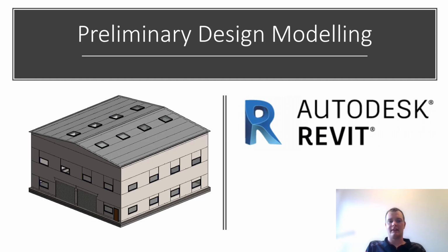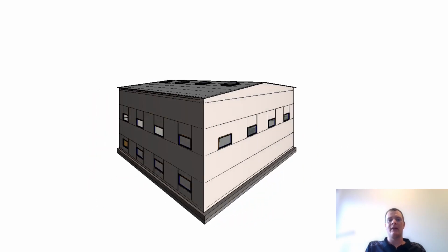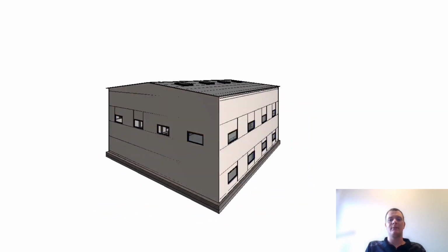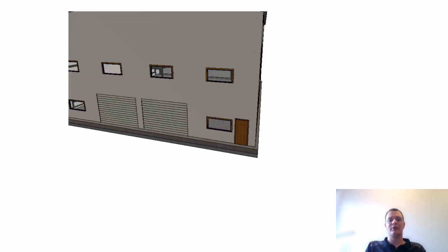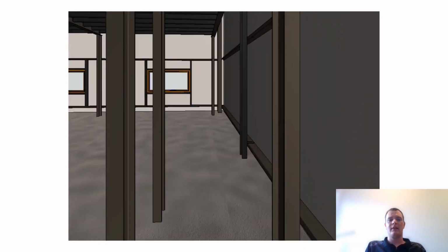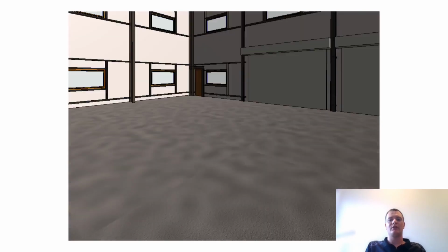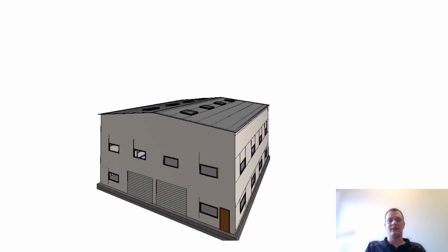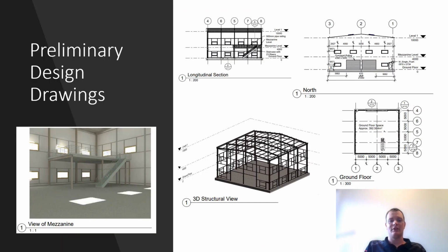As previously discussed, the preliminary design of the portal frame structure was modelled in Revit 2020. The use of this building information modelling software gave the team at Fingers Crossed Engineering the ability to model the structure with the option for realistic shading and rendering, as well as the capability of producing walkthroughs as displayed now. This allowed the model to implement all relevant engineering and architectural features, including importing structural columns, rafters, beams and slabs, sized appropriately and meeting Australian standards, as well as modelling of other features required in the design brief, such as girts, purlins, windows, doors, roof sheeting and wall cladding.